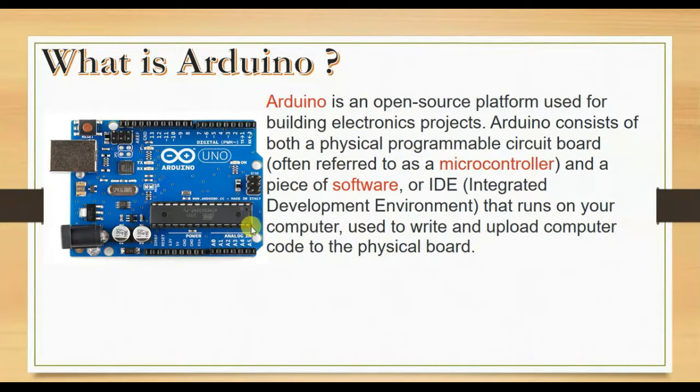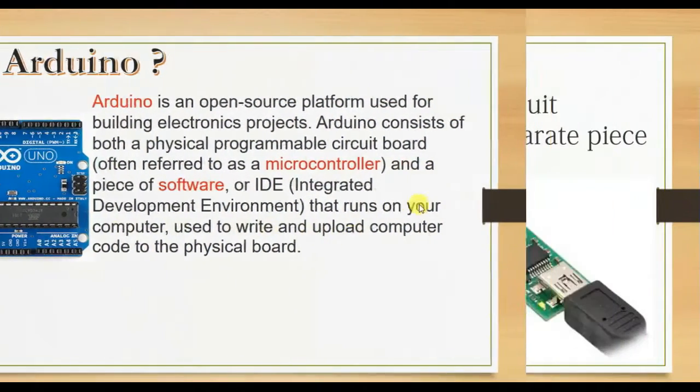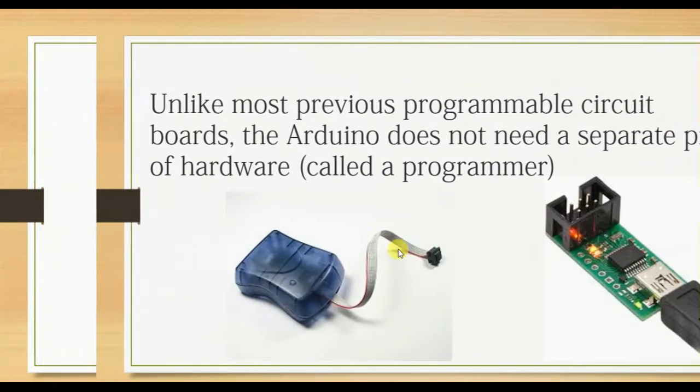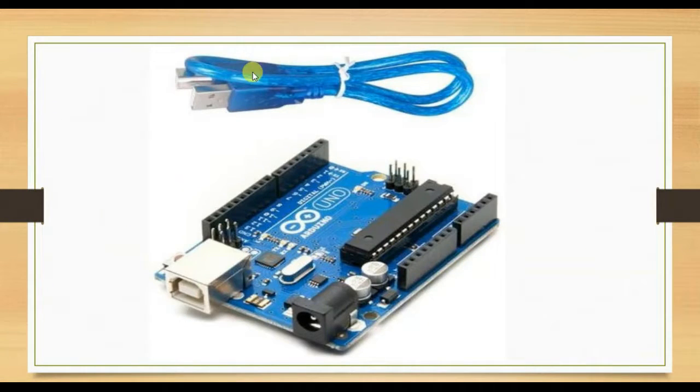This is a controller. To program that controller, we use these kinds of programmers. But with this Arduino board, we don't require these programming cables. We can directly program our Arduino boards with a USB cable because the programmer is on the board.